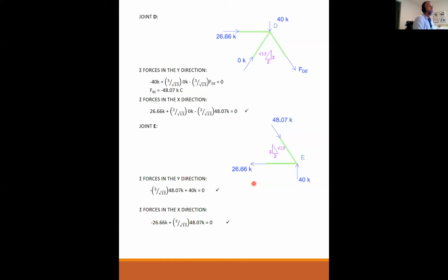Well, again, because the truss has pins at every one of these joints, you can't sum moments when you are looking at joint to joint to joint. If you use the method of sections, then, depending on how things shake out, summing the moments might work with the method of sections, but not with the method of joints. So you're not specifically using sum the moments, sum the forces in the Y, sum the forces in the X, but you don't always have to do that anyway.